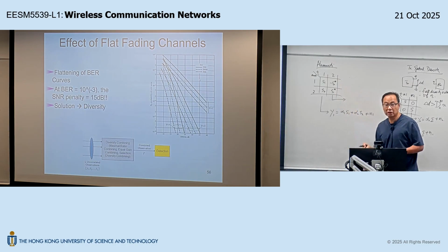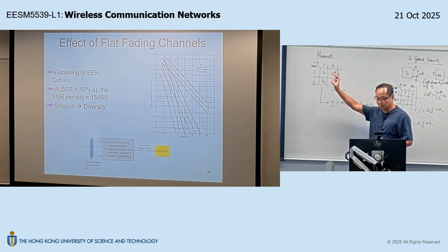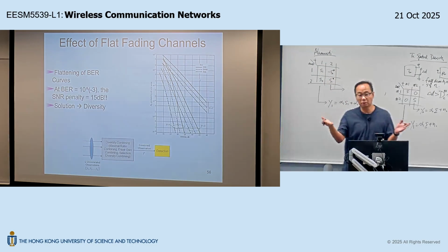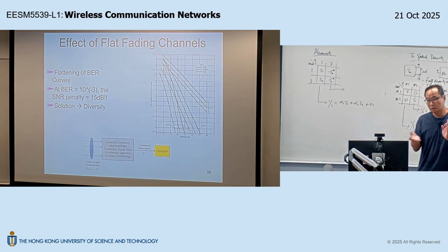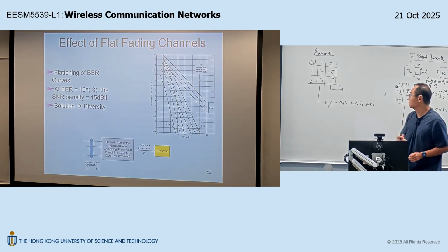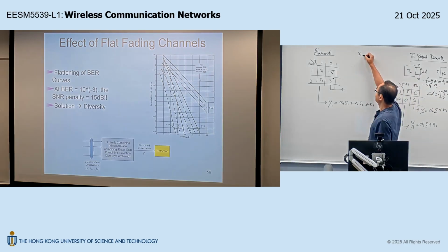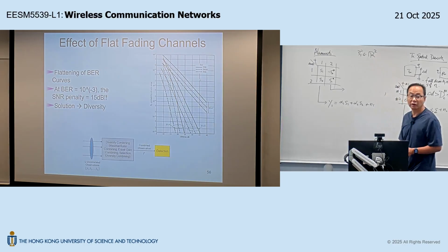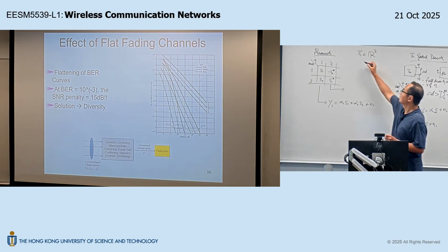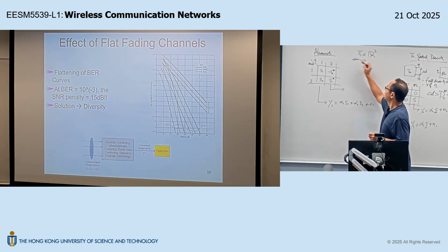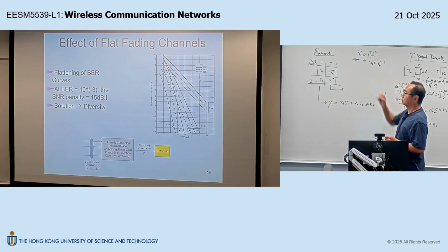Now the conjugate is a complex conjugate. So assuming we are talking about, let's say, the MQAM family, the signal space is two-dimensional, right? So you have the I axis and the Q axis. So each of these constellation points would be a two-dimensional vector, right? Each of these constellation points would be living in R2, right? But for any R2 vector, we can also represent this as a C1 point, a complex number.